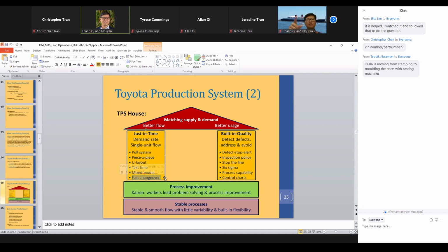So for the fast changeover, for example, in many processes, they use a barrel. When the barrel turns, then you have another bit ready to use to put another bolt or another screw of different size, right? Because you already have another bit, you can work on that right away, right? So the fast changeover capability is another thing that is important for mixed model manufacturing.